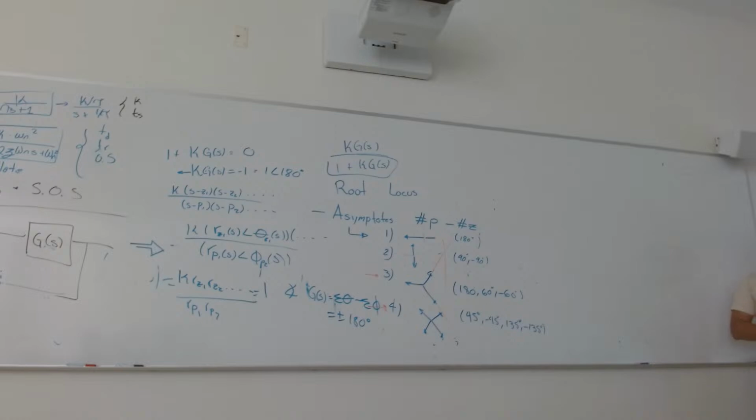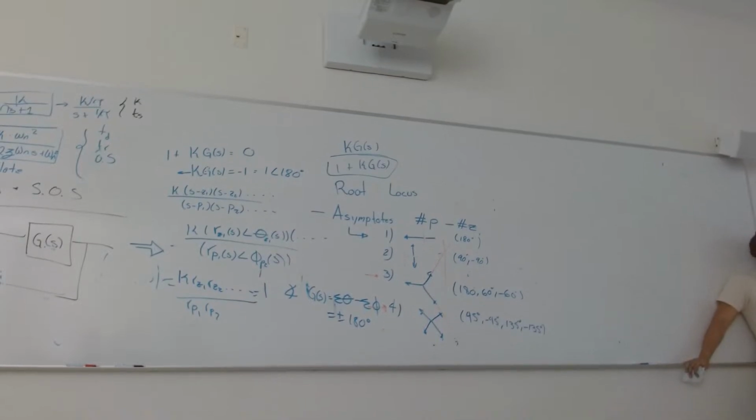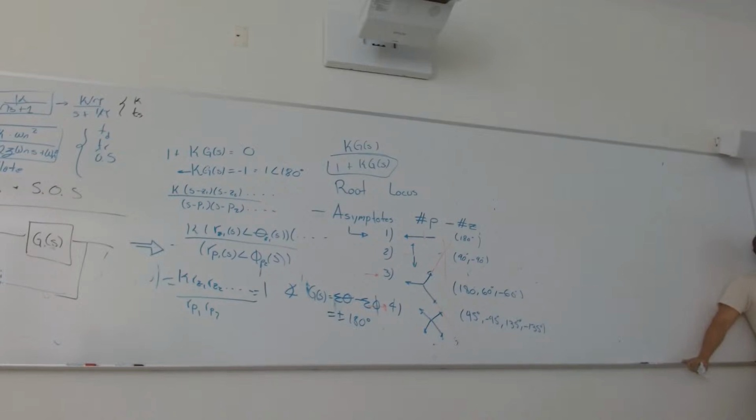And it says that if you want to use your compensator with a perfect integrator or a perfect derivator, you need to use active systems. If you don't, you need to simulate or make a false integrator by adding a pole that is really close.